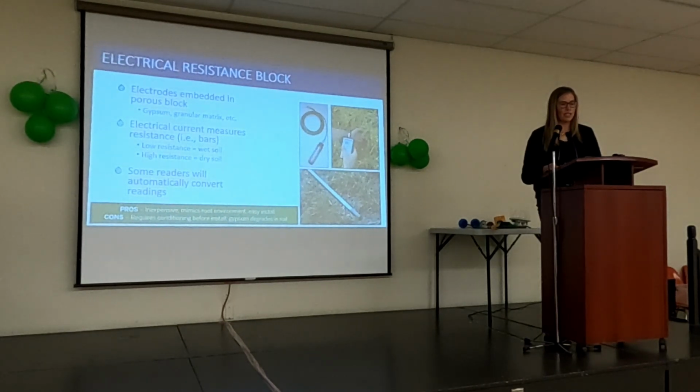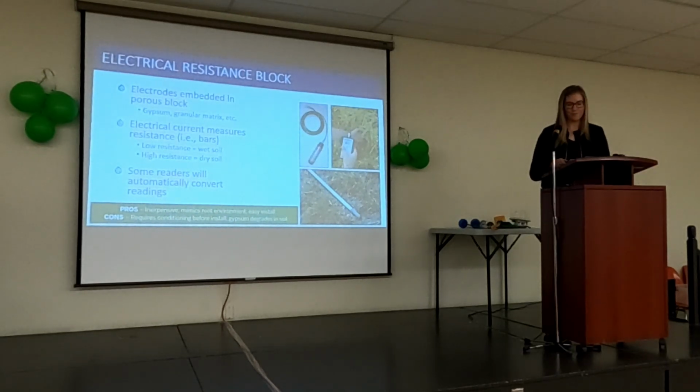And one thing I did forget to mention, the cons of them: you do have to soak them in water for 24 hours before you put them in the soil, so there's just some conditioning required. And if you do get a gypsum-based block, that will degrade in the soil over time. So I think those don't usually last for more than one field season.